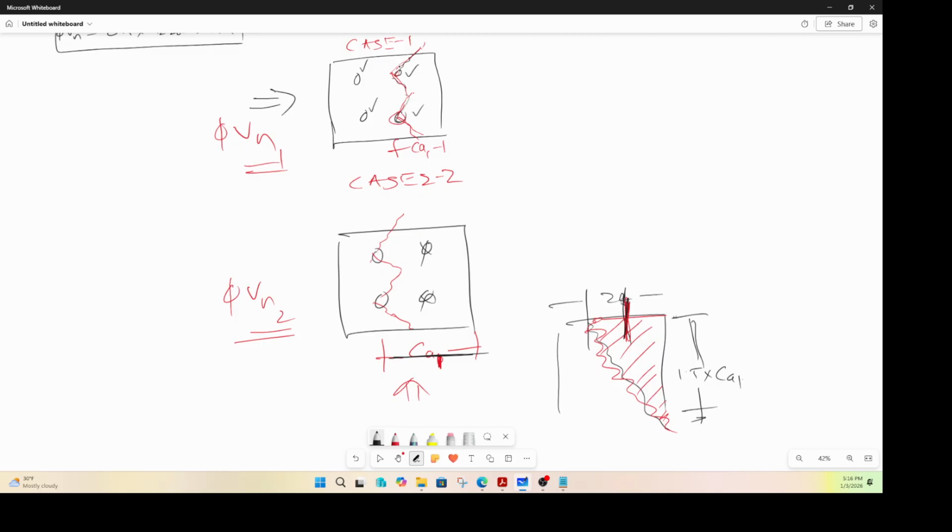Okay, so let's say the cracks will start forming at, let us say, 15 kips, right? 14.9 kips, this is active, no cracks formed, so this is sharing the load, 14.9 by 2, 14.9 by 2. Let's say this 14.9 is the entire shear acting in this direction. So that by 4, that by 4, that by 4, that by 4.